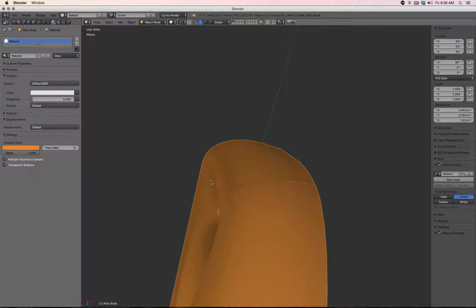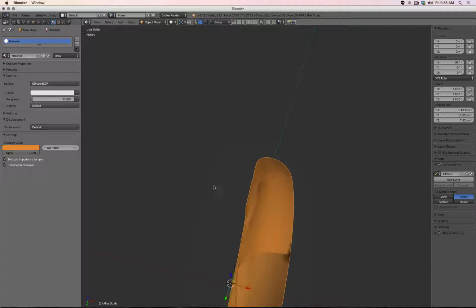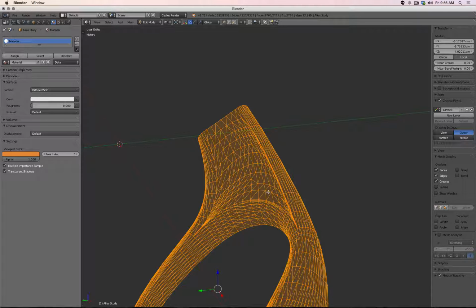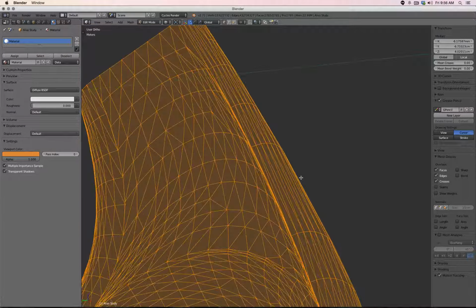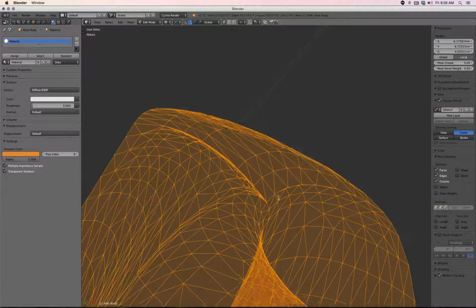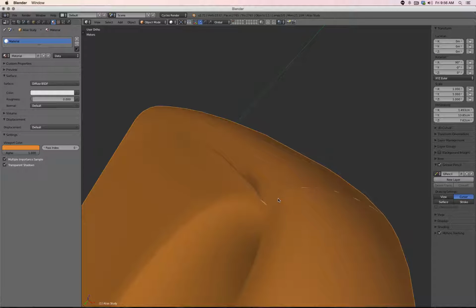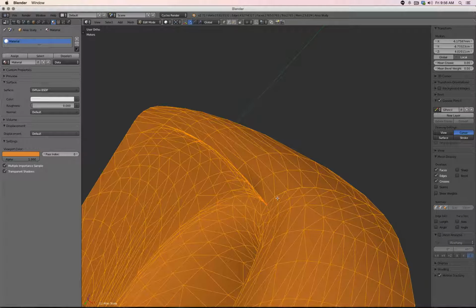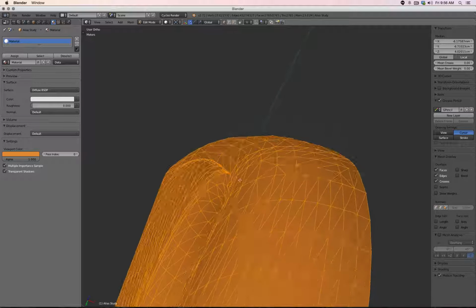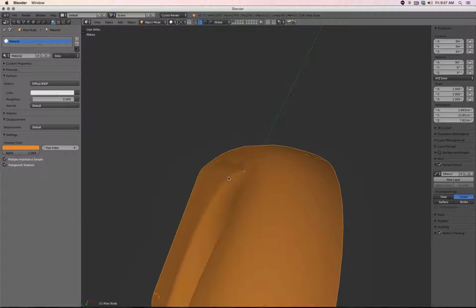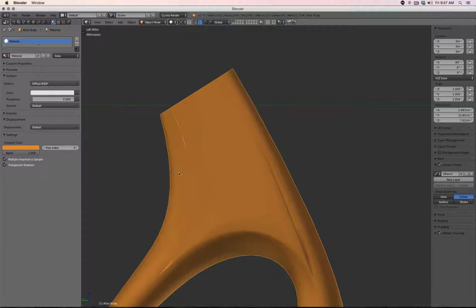Actually, at this moment, this might be a good situation to explain why, for example, all this stuff is so important. So you see, this is a really coarse mesh. If you send this one to a CNC, what the CNC is doing is taking the alias surface and then is creating an incredibly fine polygon mesh, which then can later, for example, be used for cutting or something. Or I mean, that's the same how the 3D printer also works. And yeah, so when there are problems with the mesh, the machine will be unhappy, which is why you want to have really nice and perfect transitions, because then the mesh will have the transitions as well.